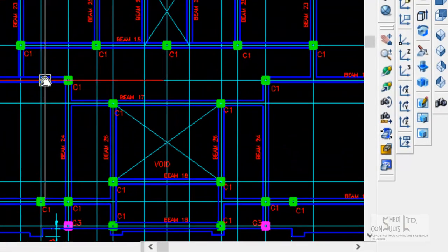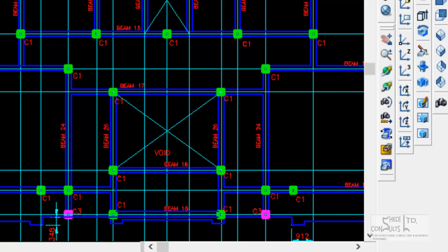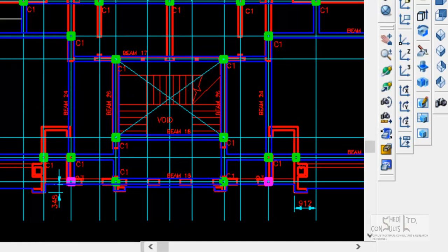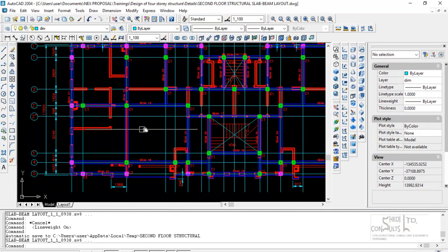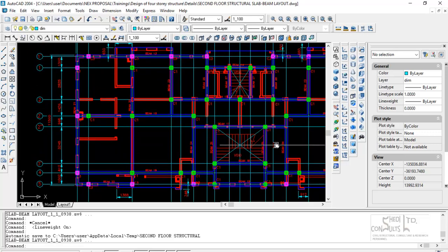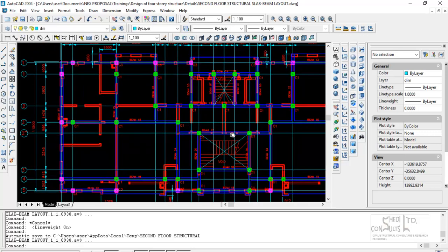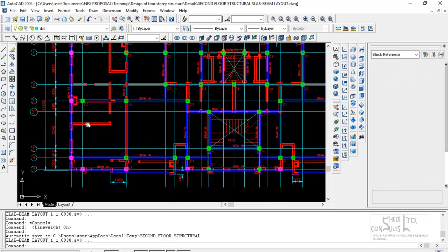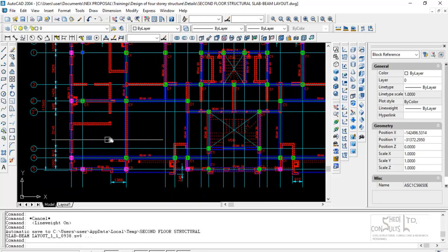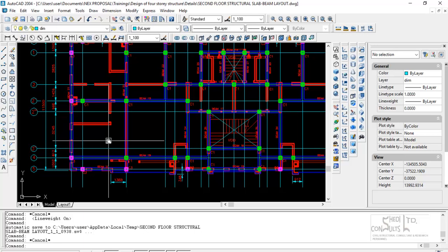So for the second floor, we use the architectural first. So you look at the first. So we use the architectural first and second floor structurals. But good thing, the first and second floor architectural layouts are both the same. So to develop the second floor structural layout, you use the first floor and second floor architectural layouts. But the first floor and second floor architectural layouts are both typical, so it's easy to frame the second floor structural layout.